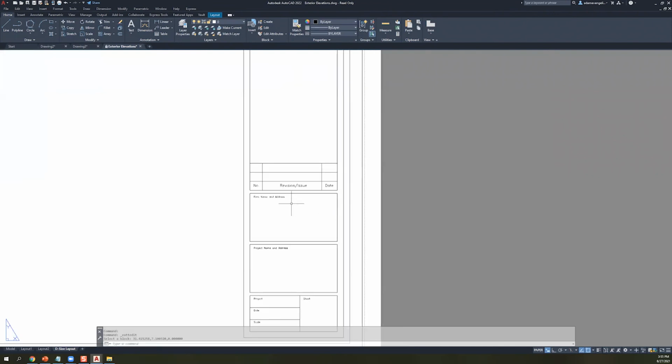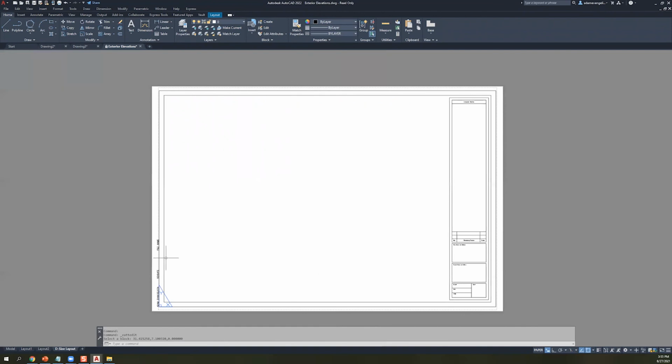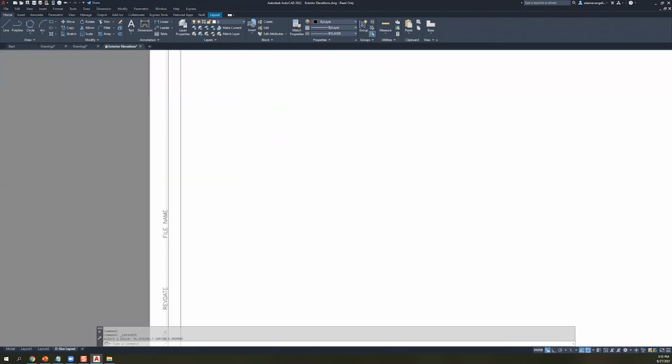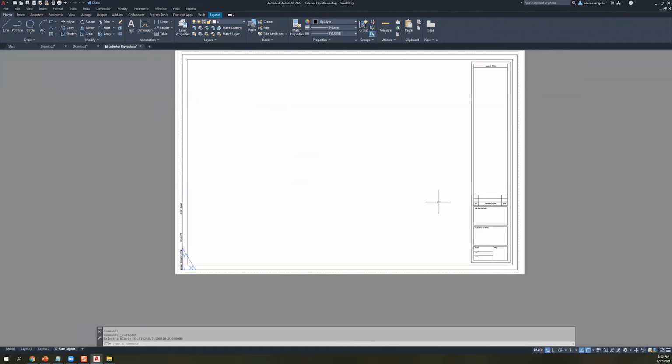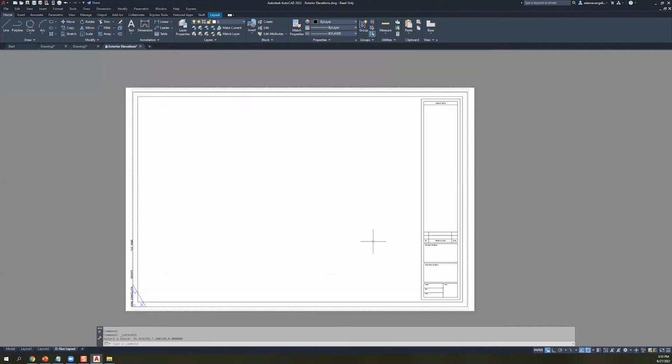And depending on your workflow, like if you have Vault, for example, there are a lot of workflows where you just pull in metadata that gets mapped automatically to certain parts of your title block. But we're not going to see that here today, so just keep that in mind. That's one way you could fill out title blocks if you have your attributes for the block set up. If they're not set up, maybe tell your guy, hey, Adam said that you could make mappable title block attributes. What's the deal? How come you haven't done that? And you could send them to me and I'll talk to them if they give you any flack.